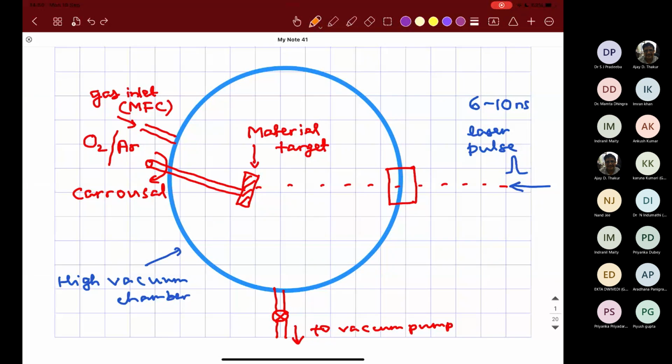Because it will have about 30 to 40 unit cells of this particular target material, and then we will have a significant amount of atoms of all the 4 or 5 varieties of elements which we are using. If it was an evaporation process, then only atoms on top would be evaporated, and depending on the saturation vapor pressure, different atoms would not have deposited in the same stoichiometry. So because of that, what we do is we try to ablate out.